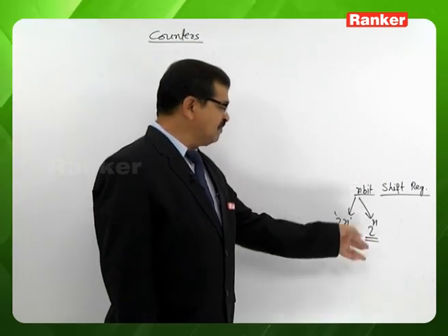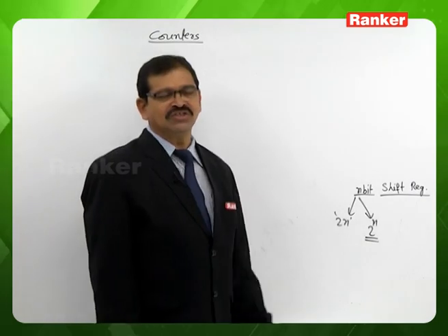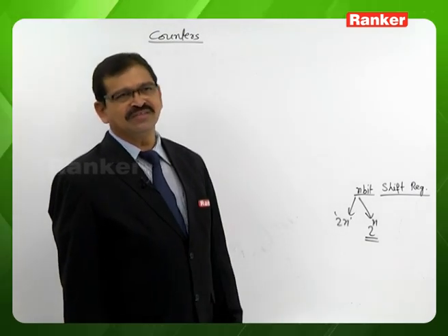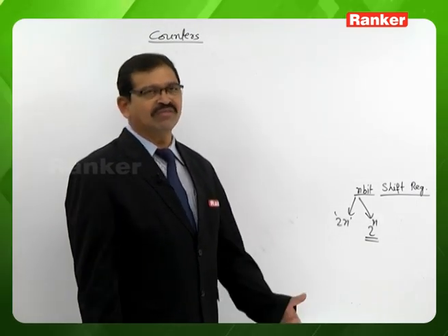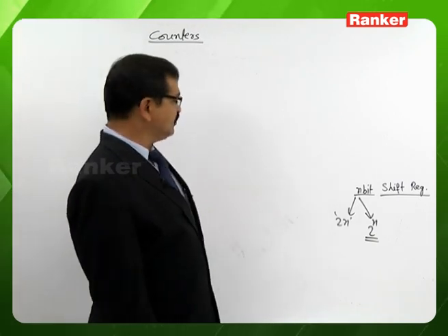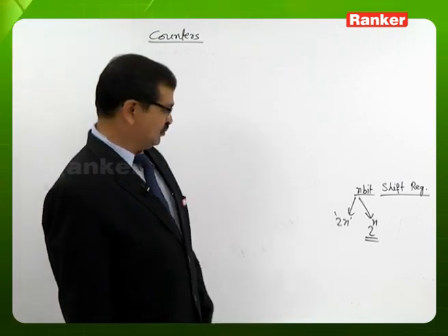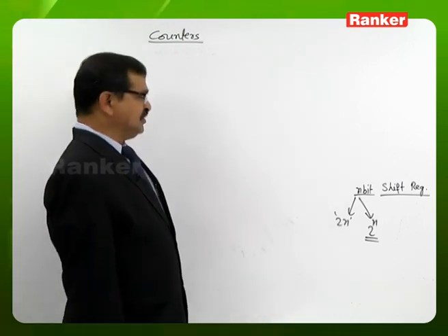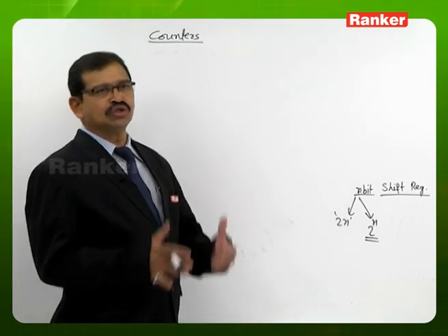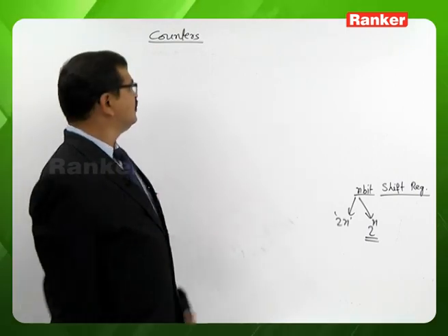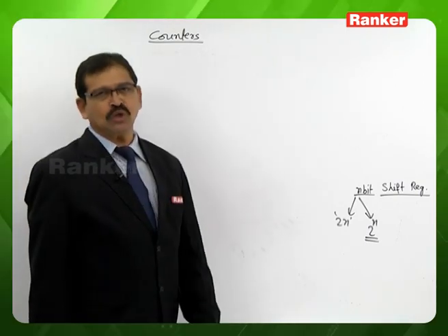With a group of 3 flip-flops, we have a total of 8 states, so when we want to have a mod 8 counter, instead of using 4 flip-flops as in the case of the register, we can use only 3 flip-flops. So anyway, there are specially designed circuits for counting clock pulses using a minimum number of flip-flops. Such circuits we name as counters.